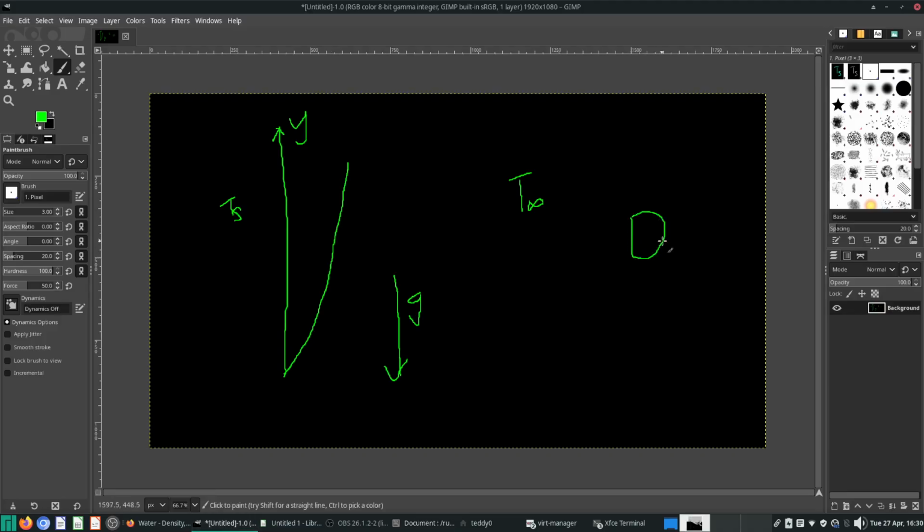The pressure at the bottom, maybe this is P at Y, and this is P at Y plus delta Y, is greater than the pressure on top. So what this is saying is del P del Y this time, no more del P del X, there is a negative pressure gradient pushing this fluid upwards.